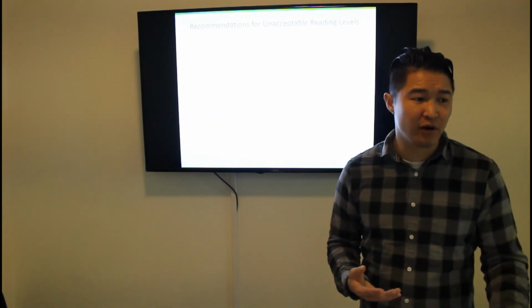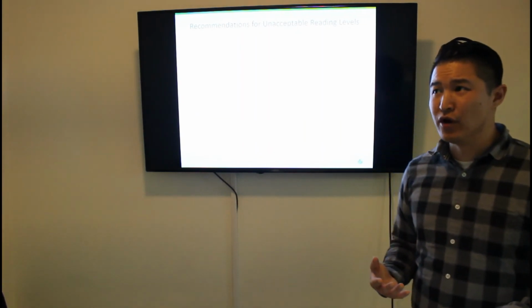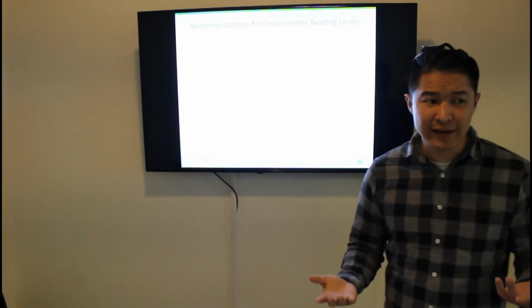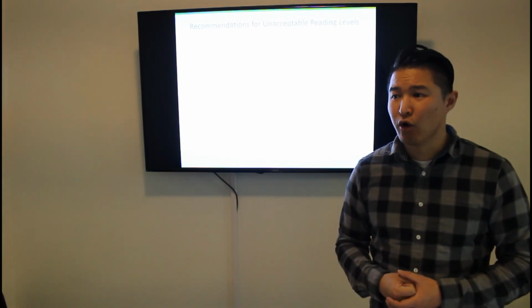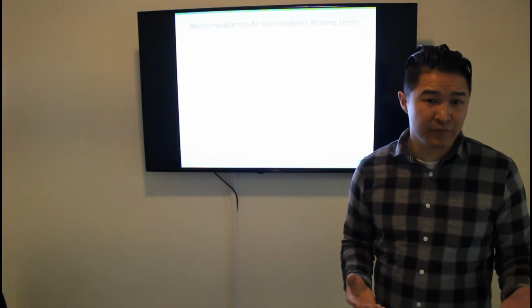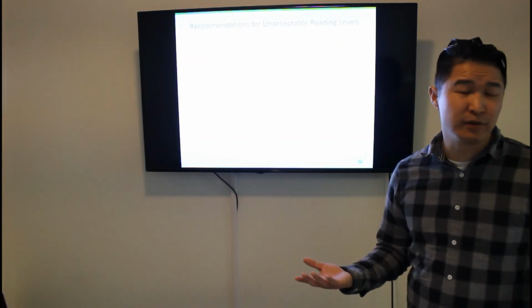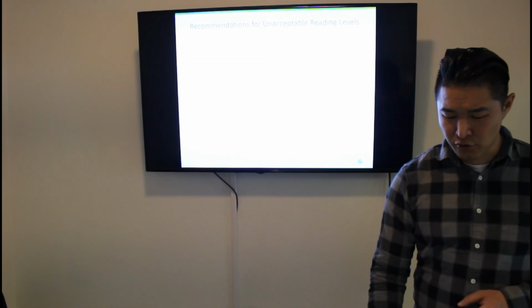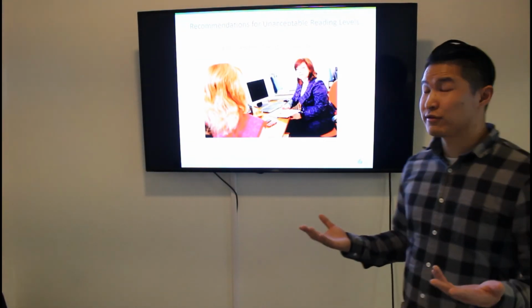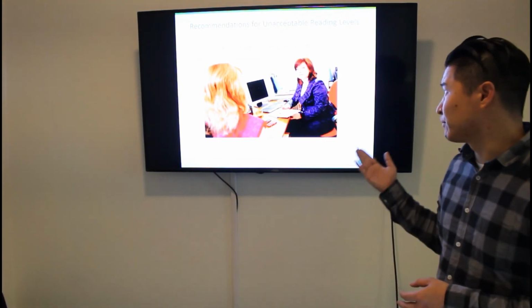I'll ask the occupants, I'll ask the property manager if they've noticed any complaints with lighting, temperature, things like that, or if they notice any discomfort. And as long as they are happy, honestly, that's the whole intent and the ultimate goal of these two standards. So if you do get readings that are outside the norm, make sure you definitely do survey the property manager or the occupants.